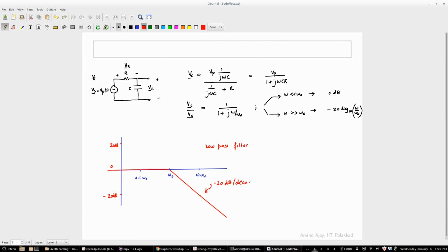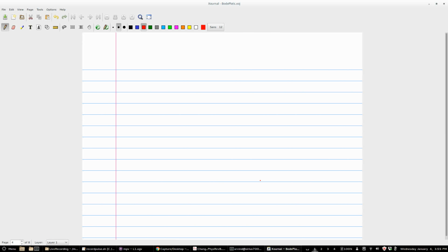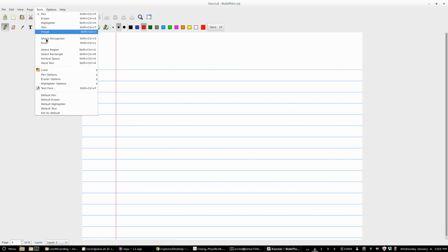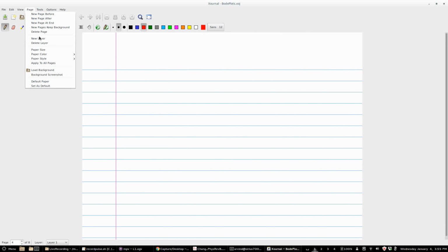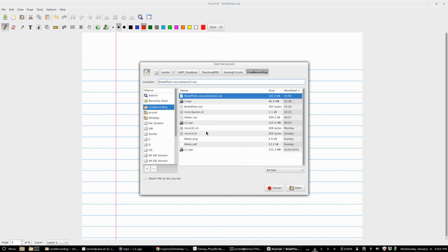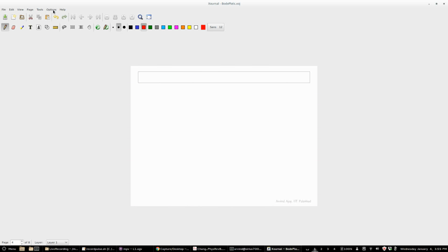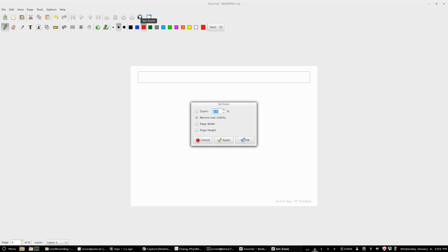Okay, so this is your Bode magnitude plot, and you see this function actually is what kind of filter? This is a low pass filter. Alright, and you have a roll off of minus 20 dB per decade. Okay. So now with this general idea, you can look at any generic function. So let's take a generic function, and with that be done.